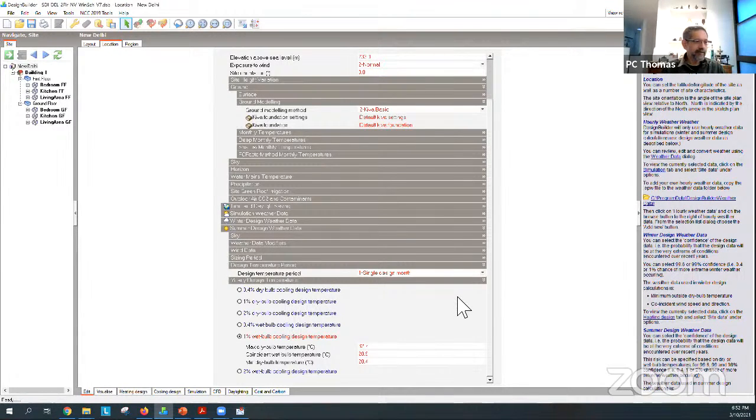Now, typically, we have gone away from doing 1 month because when you do a month, you're kind of guessing which month it's going to peak on. But really, if you've got a complex design, a lot of shading, different kinds of glass, different thermal mass, then the angle of the sun, the shading devices, what's happening inside the building can make the peak not necessarily in the summer months, but it could be in one of the other months.